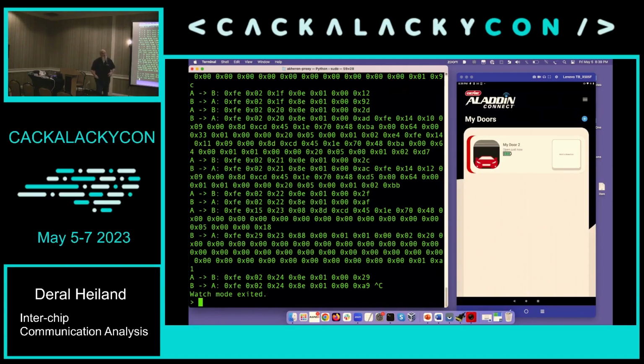And the reason why ANT is used in a particular case like this is because another device can connect to it. BLE can have one connection, and ANT can have multiple connections. By using ANT instead of BLE, you don't have that conflict in that particular case.